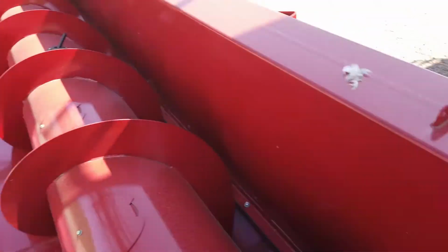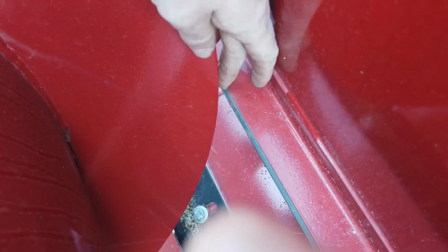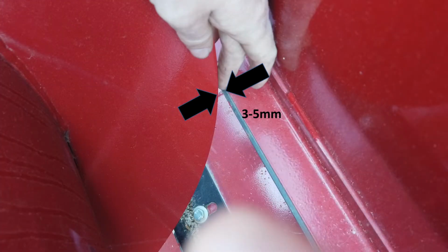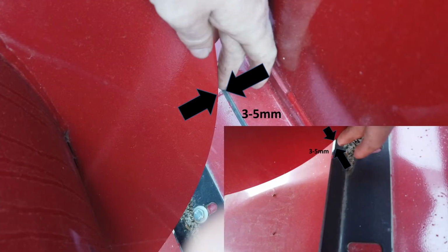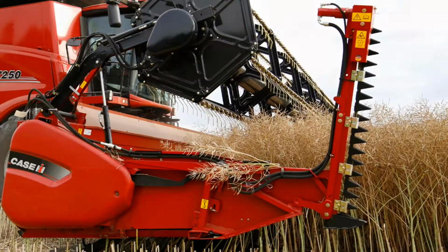When the auger flight and tine clearance have been set, then adjust the stripper plates towards the flights. Loosen the bolts and slide the strippers to achieve a clearance of approximately 3 to 5 mm. When done, run the combine and check for any interference during the full raise lower arc of the header. If this is not done, then there is every chance that wrapping on the auger will frequently occur.